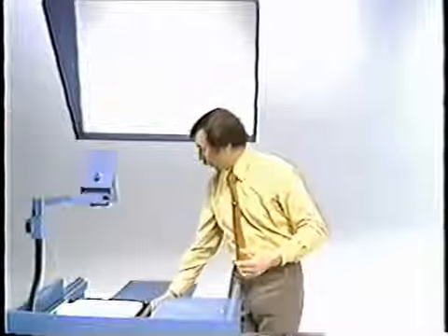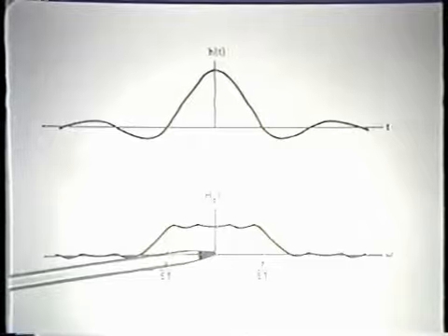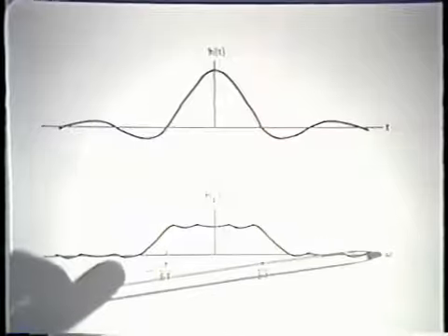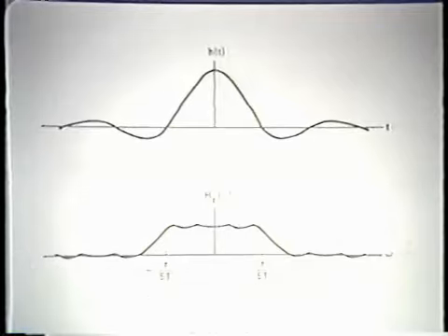Or if we look at the corresponding continuous time frequency response, what it means really is that sweeping from 0 to 10 kilohertz is moving up this way, and then sweeping from 10 kilohertz to 20 kilohertz on the input, really because of the aliasing, reflects itself in the digital filter by looking back down toward lower frequencies, and so the continuous time filter sweeps back down from 10 kilohertz back to 0.